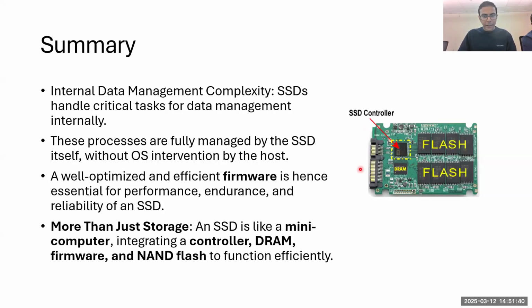So this itself makes this solid state drive a mini computer, right? A lot of data management happens within the solid state drive without any intervention by the host. That means we would need a well-optimized and efficient firmware running on it to manage data efficiently for performance, endurance, and also reliability. So the SSD is not just storage, it is like a mini computer where we integrate the controller, DRAM, the firmware, and the flash storage itself to function efficiently.